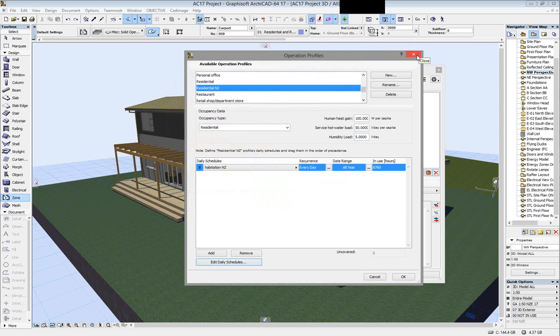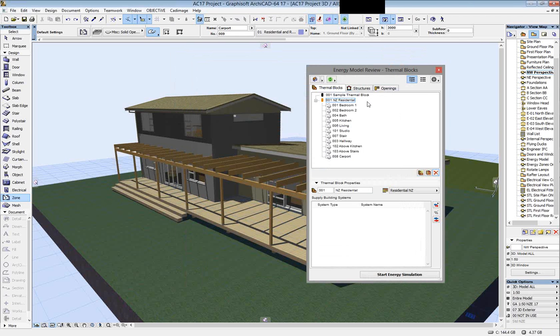The other one that is now covered is model-based irradiation studies. It sounds rather complex, but what it does basically is it analyzes the amount of sun that hits each window. It just means its analysis is much more accurate. It's also worked out based on the model. So if there was a tree in the way, it would know when the leaves fall off and when the sun is going to be behind the tree, therefore less sun is going to hit it. It gets quite accurate.